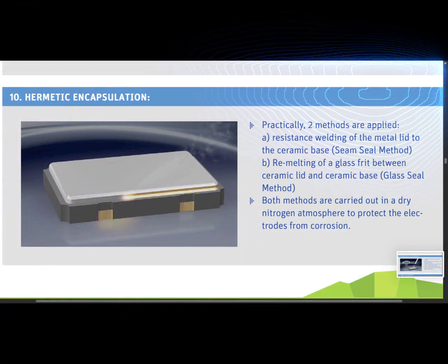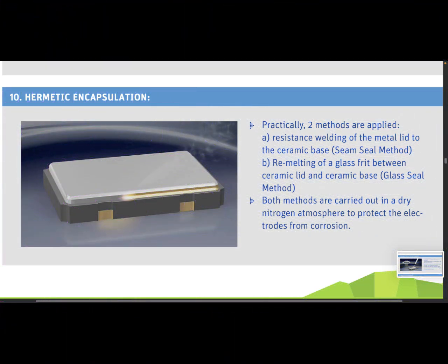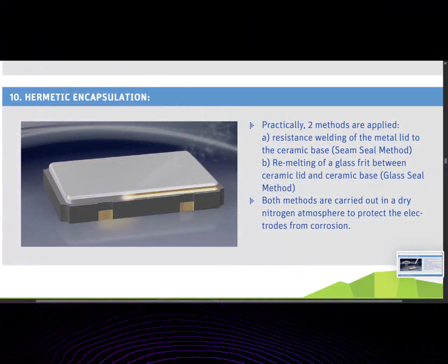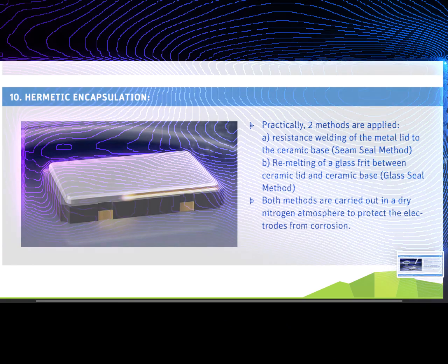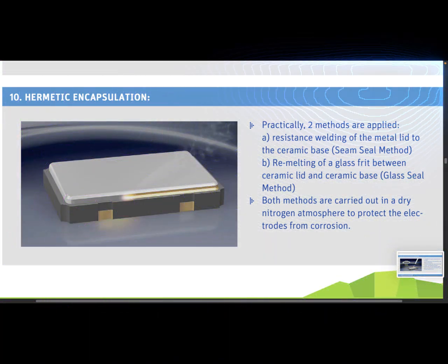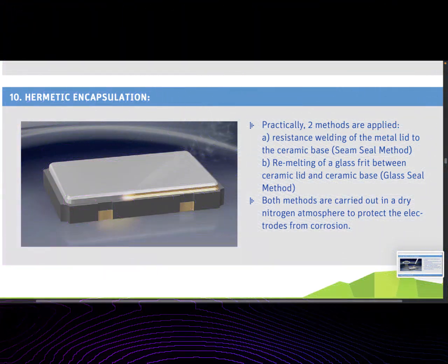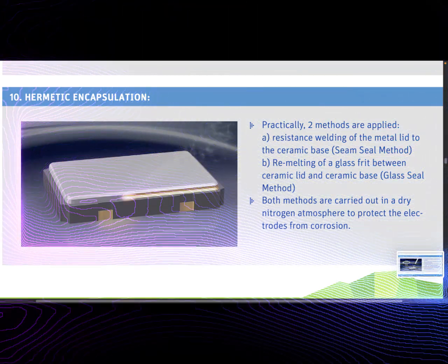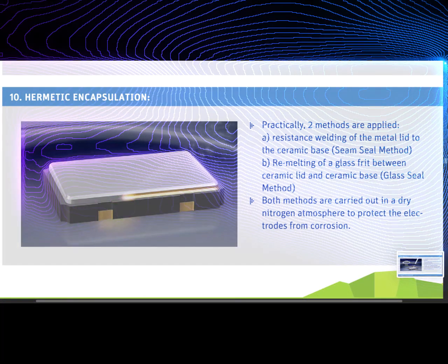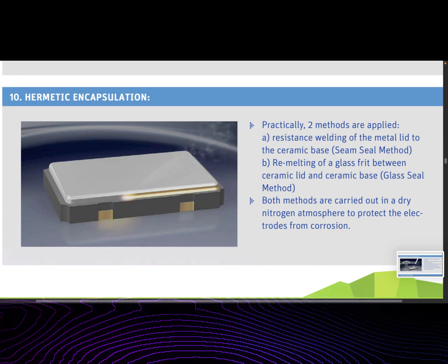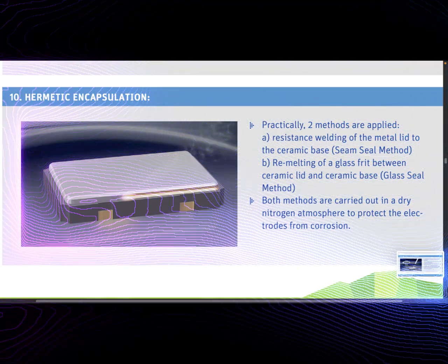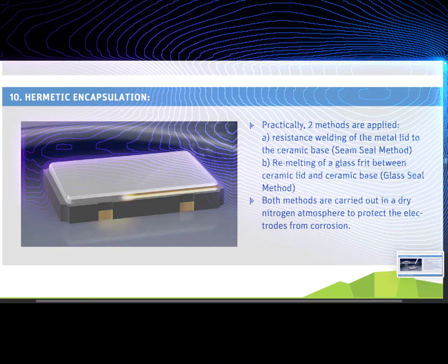So, the piezoelectric effect in a crystal. A quartz crystal resonator consists of a thin piece of piezoelectric material, precisely dimensioned and orientated with respect to the crystallographic lattice. This so-called crystal blank has a pair of conductive electrodes that are sputtered or evaporated on some surfaces of that crystal blank in a vacuum.